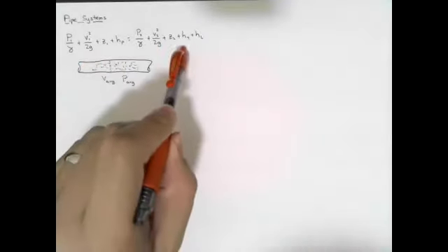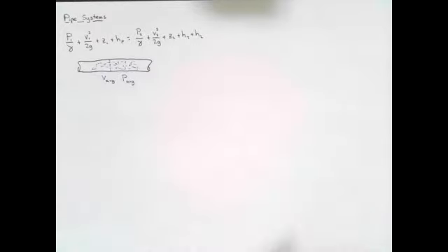remember that we had our pressure, velocity, and kinetic energies for two different points in a control volume. In this case, my control volume is my pipe, or the length of the pipe that I want to study. We mentioned that HP was pump head, HT was turbine head, and HL we mentioned was head loss. In other words, we looked at the energy that we added to a system, removed from a system, and then the energy that we lost.